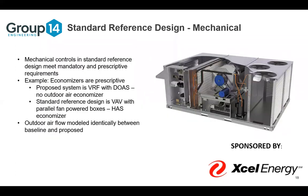The mechanical controls in your standard reference design, or your baseline, should meet the mandatory and prescriptive requirements within the code. A good example here is if we have a proposed system with VRF and DOAS, they are not providing an outdoor air economizer. And the standard reference design for that same system, we can run through it if you want to, is VAV with parallel fan-powered boxes and electric reheat.